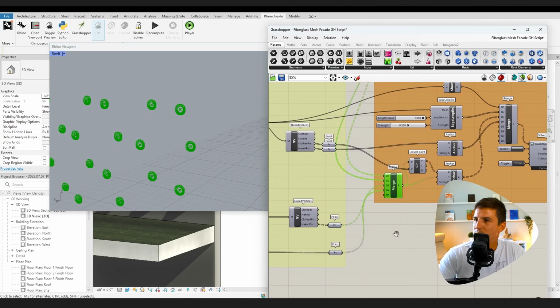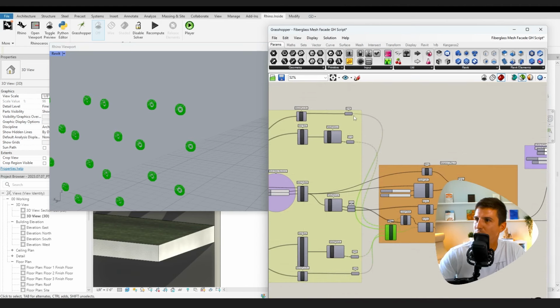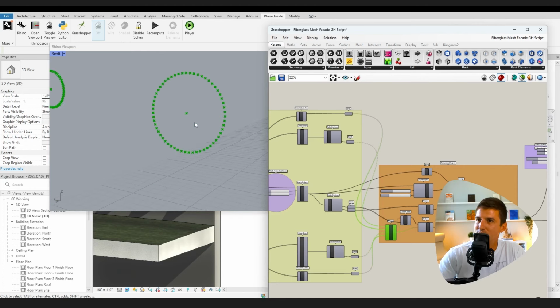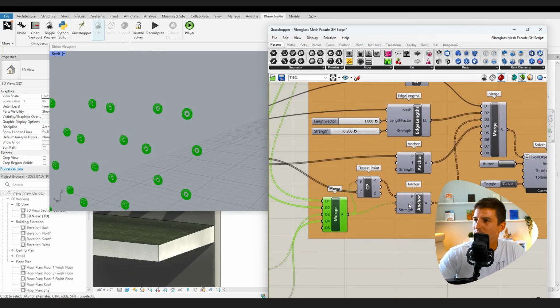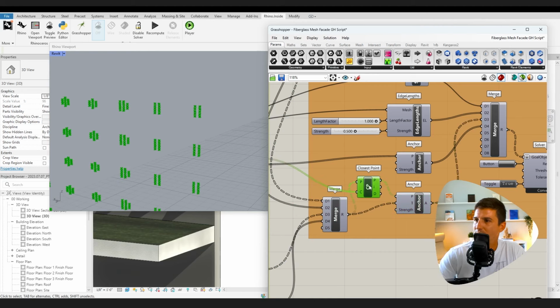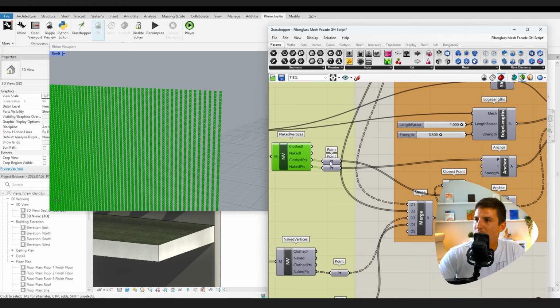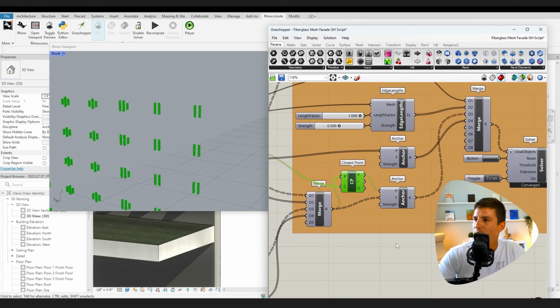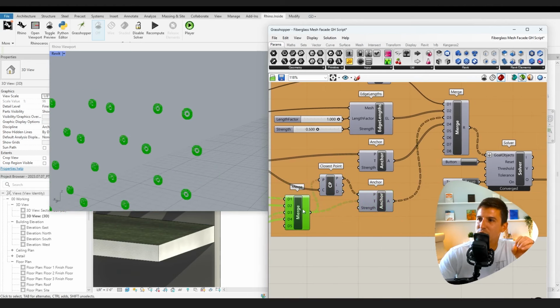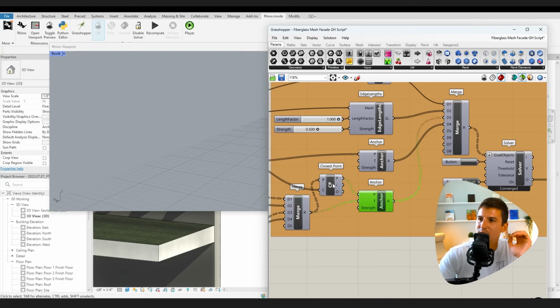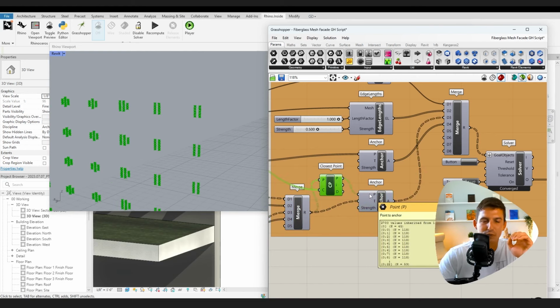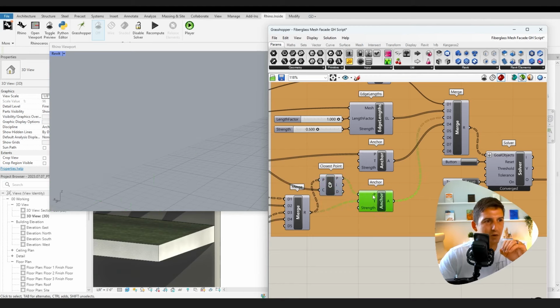Notice that this merge component is using the data from both circles, their perimeters, their naked vertices, as well as their center points. And that's going to be brought in as an anchor and reference to the closest point that is on the mesh. With that closest point, we are going to make the circles the target for where the closest points on the mesh relative to those circles need to go. This is the part that confused me the most the first time I was making the script.